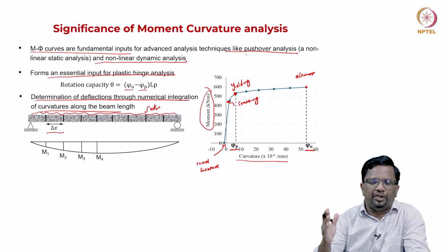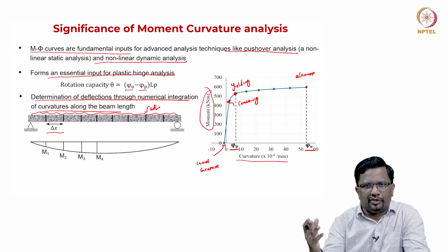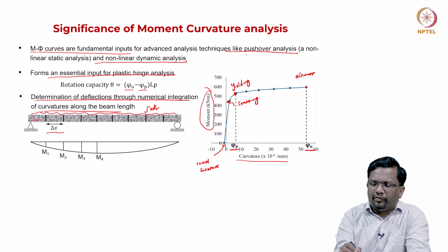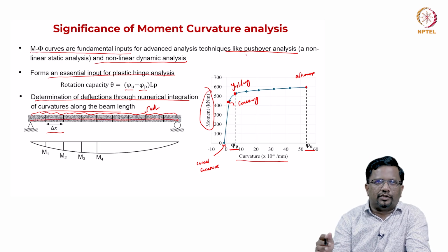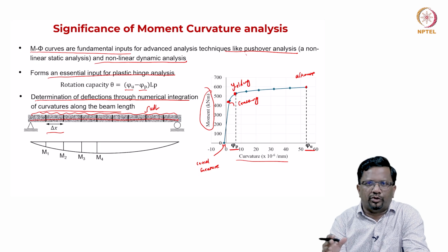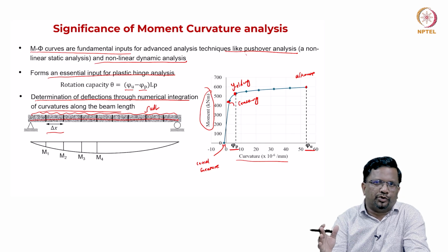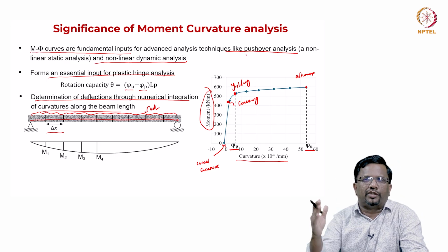Then for this beam again we know the cross section details, we are going to assume what is the steel from your design, right. So, for simply supported case, now I am going to have reinforcement somewhere in the bottom like this, right, because the tension will develop at the bottom. So, I am going to put steel on the bottom side, right. Now, if the reinforcement configuration does not change, then every cross section is going to be same.